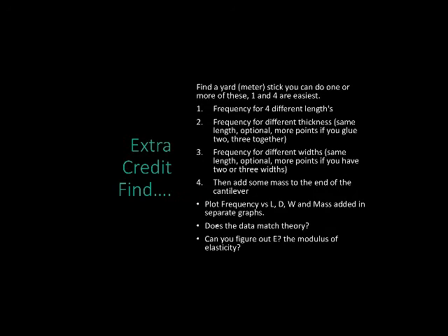Okay, so do it for 4 different lengths. You can try different thicknesses. You can glue 2 sticks together if you want. Not required to do all of these, just do one of them. Do different widths if you can. And then you can look at frequency versus length versus thickness versus width. You'll find out that the thickness changes the frequency, and the length changes the frequency.